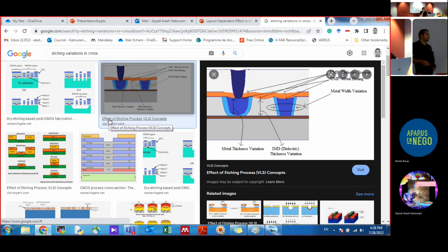For example, if you have an array of capacitances and you need, say, a DAC or something like that, and you have the bits 2, 4, and so on. Say you have a bit of 8, for example, here. The one in the center will be etched differently from here. So when you go to ×2, ×4, you will not have the same multiplication. So you have some mismatch there, because it is not linear. For the matching, we also use the center approach.